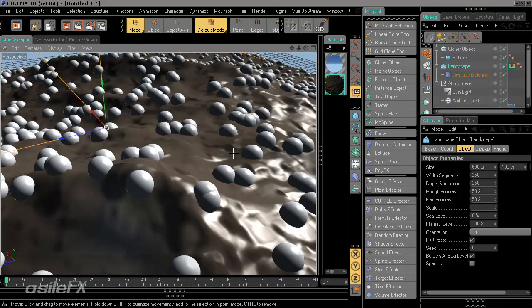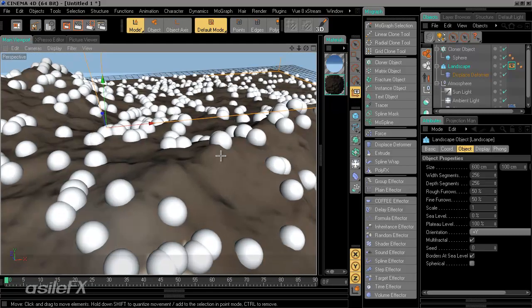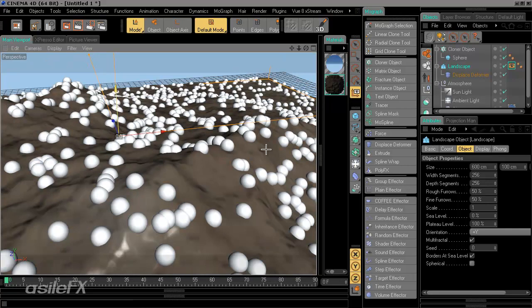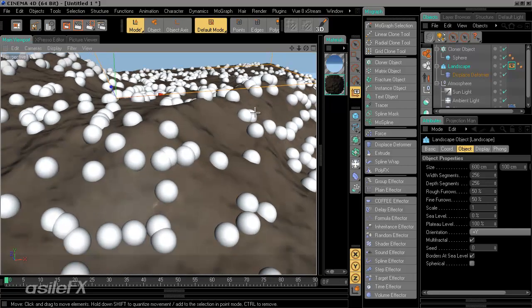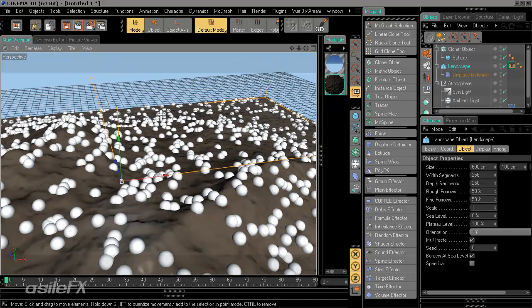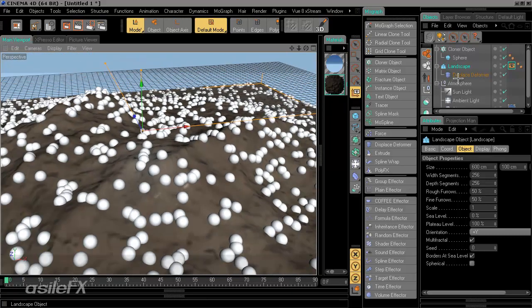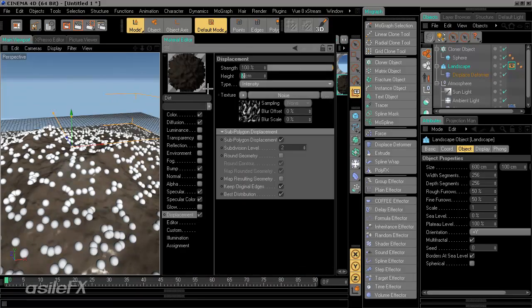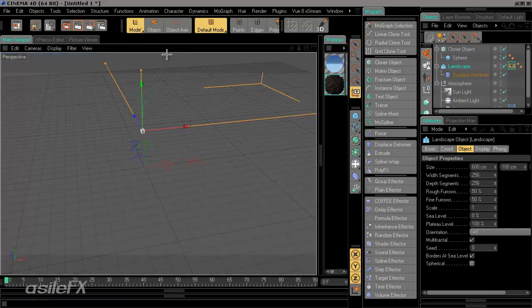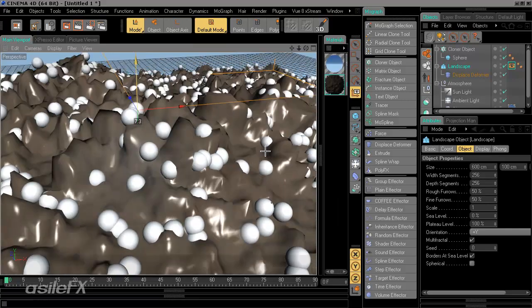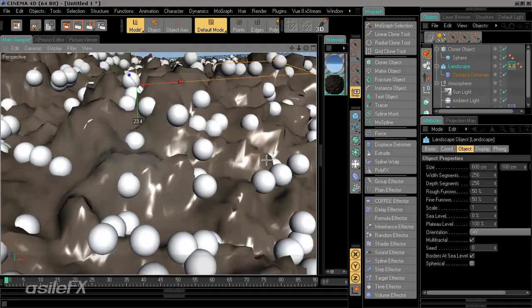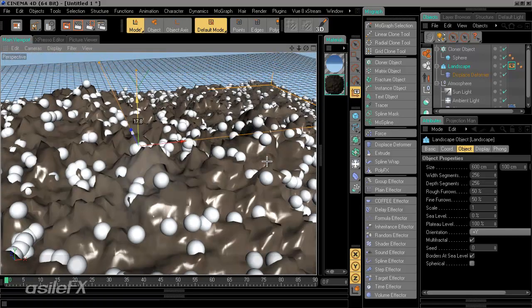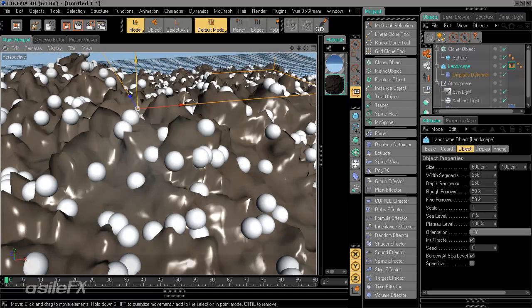And it's probably going to be kind of difficult for you to see it within the recording. If you take a look at the cloned objects, they should shift around and move a bit. But really that's because the intensity isn't set very high. Because back in the emulation mode is using the intensity of the material, which is reduced to 2 at the moment. So we'll go ahead and bring that up to 15, make it really high, and now we should see that displacement moving through the terrain. So it'll even move the clones with it, kind of jumbling them around. Can create some pretty neat effects.